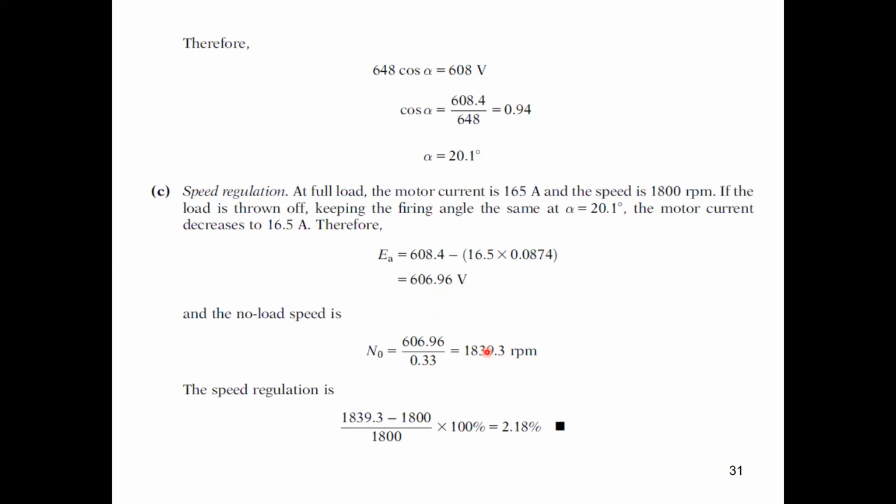Is it clear? And for any curve, for any voltage value, we will have different no load speed. And if we would like to plot the characteristic now, this is, for example, the relation between speed and torque at a certain voltage.